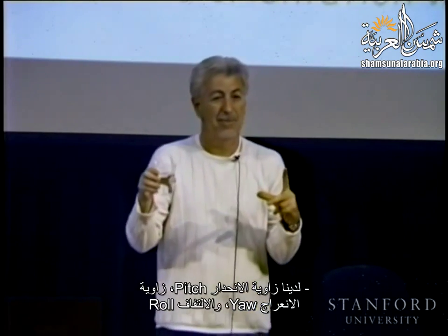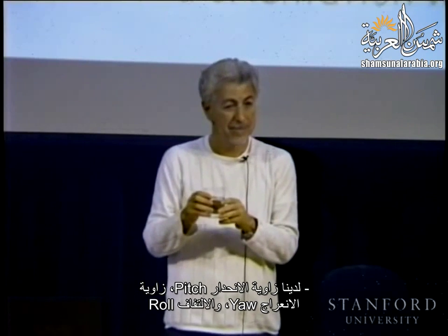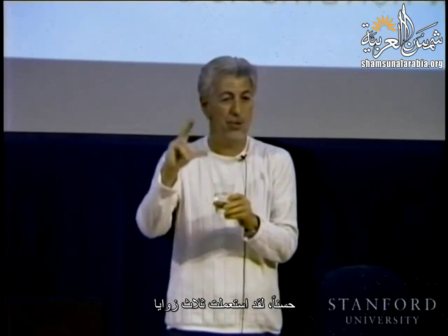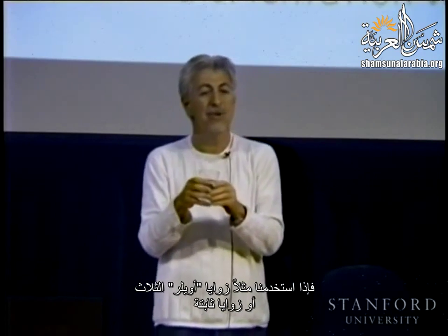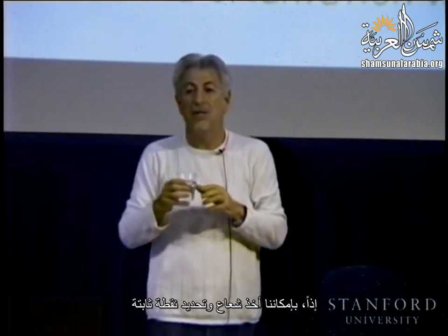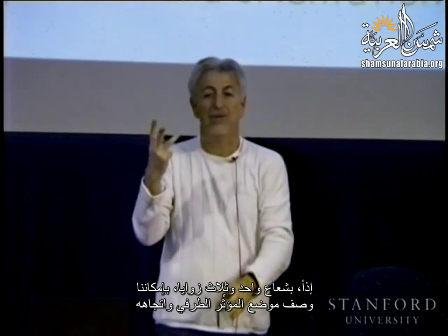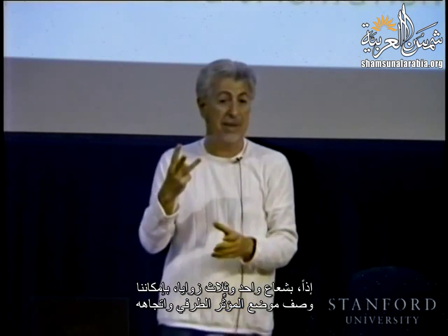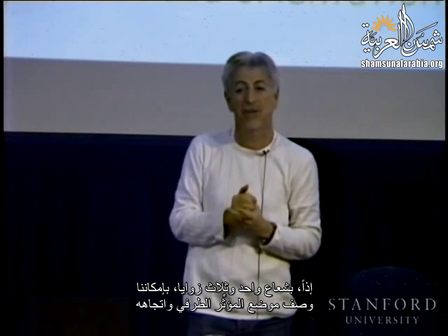Well, for the orientation, sometimes tilt, yaw, and roll. Okay, you use 3 angles. So if we use 3 Euler angles or fixed angles, we can find this position and orientation for the end effector. And for the position, X, Y, and Z. So we can take a vector and locate one fixed point. So with one vector and 3 angles, we can describe the position and orientation of the end effector.